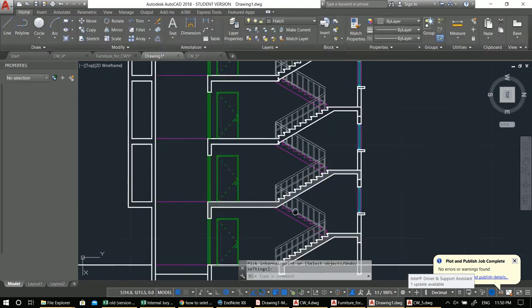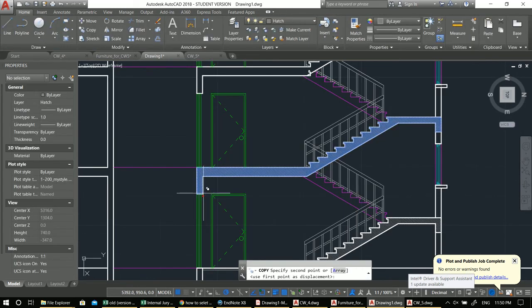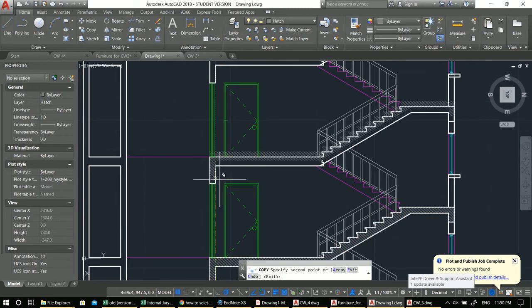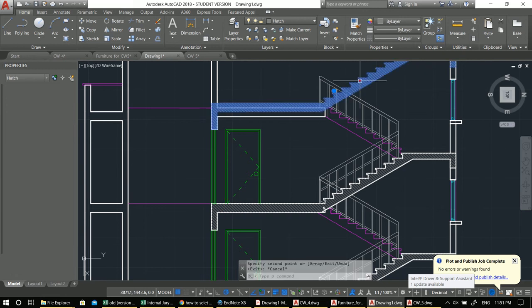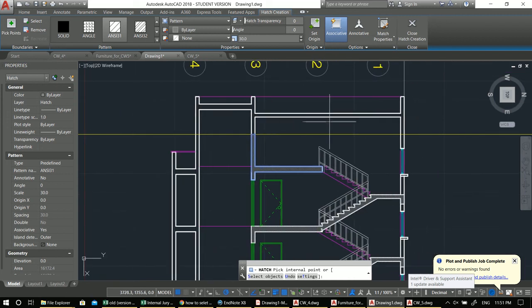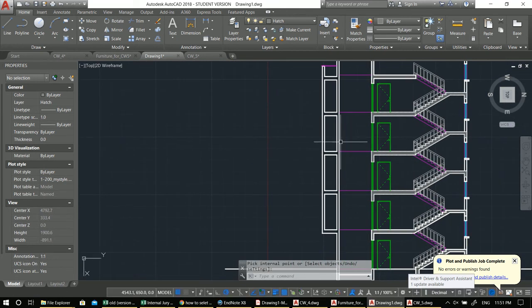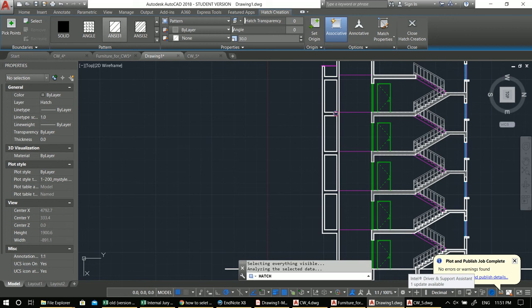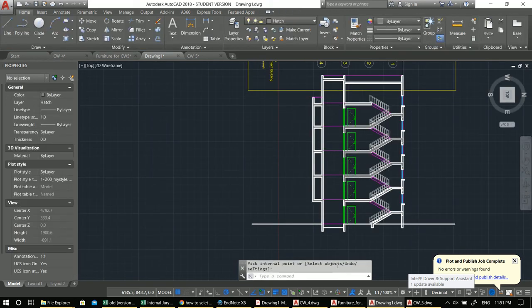Okay, now it's okay. Again, here you don't have to do it one by one. You can just make one and copy it up. Or the hatch also works perfectly. Not for this one. For this one we have to go and hatch it. Oh, we are already entering our drawing area. Don't be greedy while hatching. Don't try to hatch everything at once. Just go out and in and try to break it into pieces, because if it's too big, and if you're like me and you don't have a very good computer, it might create some difficulty for you.